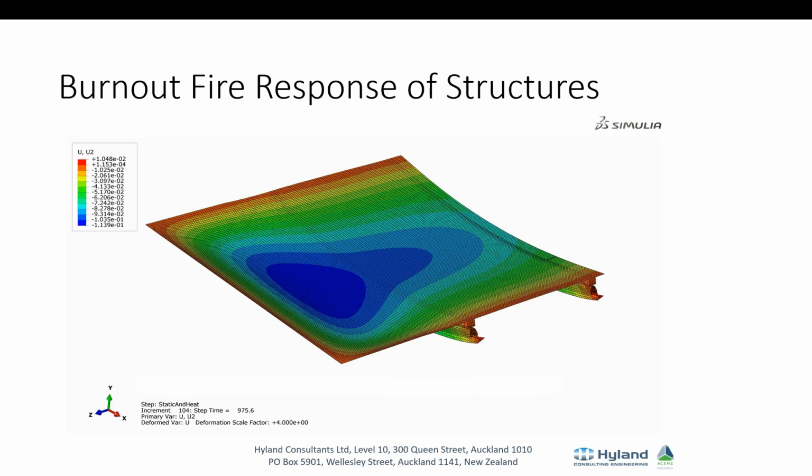One of these is fire responsive structures for the burnout condition where the sprinklers are assumed not to be operational, and the effect of this can mean that safe egress paths or perhaps stairs that might be supported by composite steel beams and floor slabs may be susceptible to deformations that could lead to smoke or breach of fire line walls, say gib walls, and also potential collateral damage and even perhaps leading to collapse of egress stairs. So this is something that needs to be worked out.